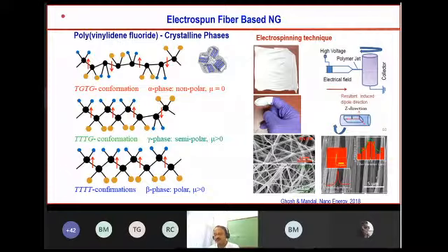When the strong mutual electrical repulsive force overcomes the forces of surface tension, because surface tension force is there in the polymer solution, then you can find the polymer jet, and one can collect the polymer fiber. And you see, after collection of the fiber, you can see the product, which is like the electrospun fiber. It is very porous, and one can make any desirable shape.